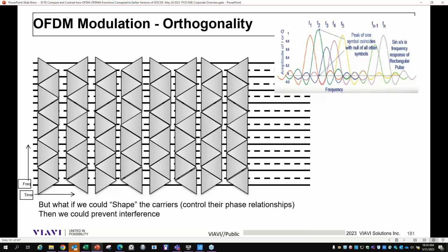Absolutely. And there is intercarrier interference. It has to be verified, but those type of things. But man, it is amazing to see the speed in which this modulation occurs. Yeah, it is quite amazing, and the spectral density is just so much more dense than SC-QAM. And like you said, 30%. You're increasing your spectrum efficiency by 30%, OFDM versus SC-QAM.